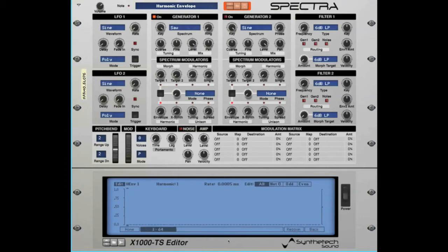Note the Harmonic Envelope Edit screen displays a range of 64 stage elements relative to the selected harmonic. The scroll bar at the bottom shows your location within the Harmonic Envelope stage and enables you to scroll through all 256 stage elements. To edit stage elements, you can select the element you want to edit and, holding the mouse button, drag the value to the level you desire.